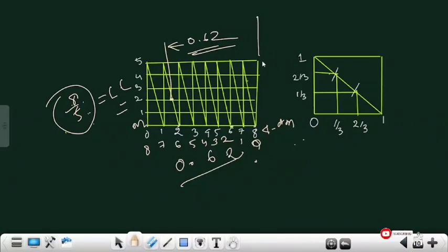In a plain scale we can't divide 3 consecutive numbers, but we can simply draw a diagonal, so we can easily divide it into sub parts and measure up to three consecutive numbers. This completes the scale chapter.